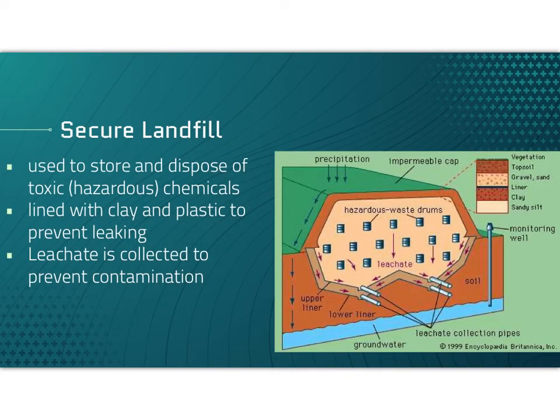A secure landfill is just slightly different. It's used to store and dispose of toxic or hazardous chemicals. It is also lined with clay, but also with plastic to prevent leaking. Leachate is again collected to prevent contamination. So we have this actual liner implemented here as well. And we're not looking at the production of gases. We are just basically storing this hazardous waste. It likely won't break down. We are trying to just keep it contained.